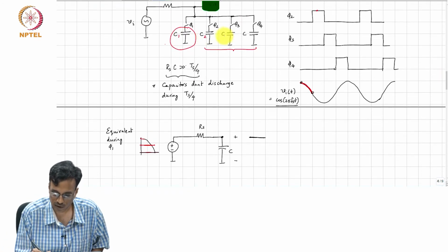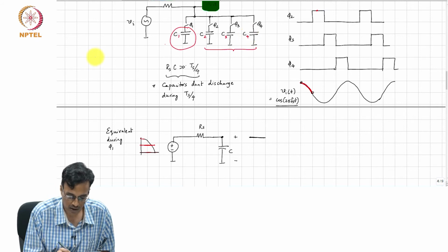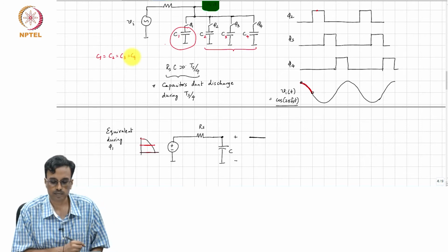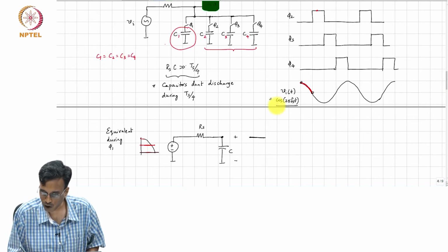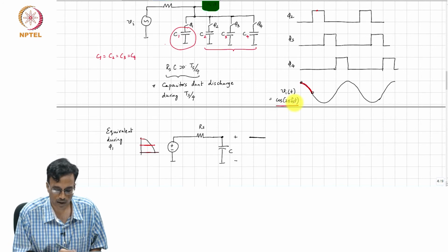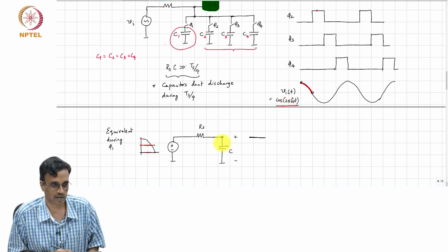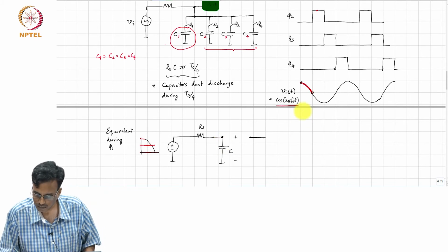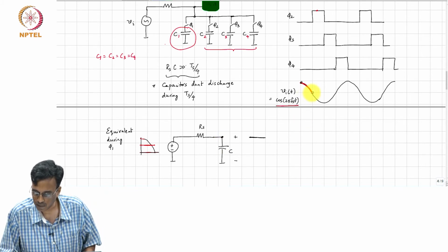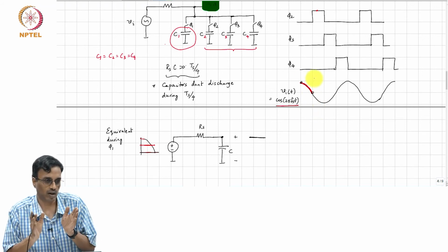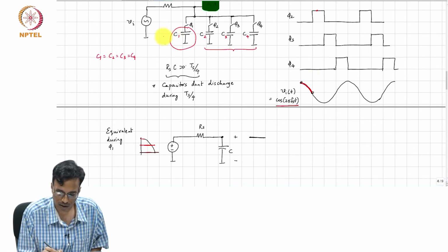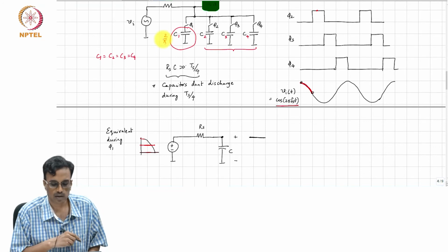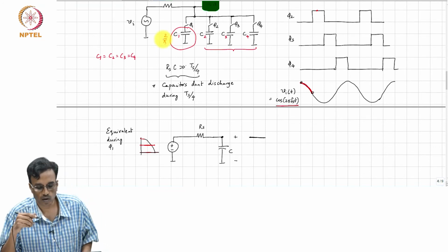I am going to call these C1, C2, C3, C4. So, VC1 equals VC2 equals VC3 equals VC4, all right. In steady state, therefore, with an input of cos 2 pi Fs times t, the average value of the voltage sitting across the capacitor C1 will be what? What do you call the average value of a quarter cycle, which is 2 by pi, right. So, this voltage will be 2 by pi on average, right. That is the voltage stored on C1.